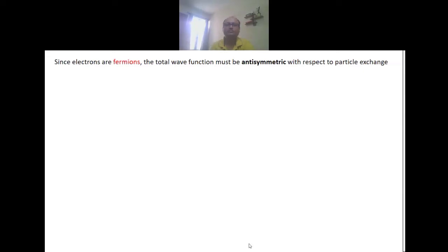Our group recently published this work for making the RAM. As I showed previously, we can create germanium nanocrystals within the MOS structure, but this is not the end, because they have their own dimensions, so we cannot scale further. That's why we have to work without using any nanocrystals. Here we are utilizing a simple matrix, where the oxygen vacancy is controlled. We use the ion beam technique to control the vacancies, and I showed that the vacancies are really formed, which we confirmed by the experimental result.